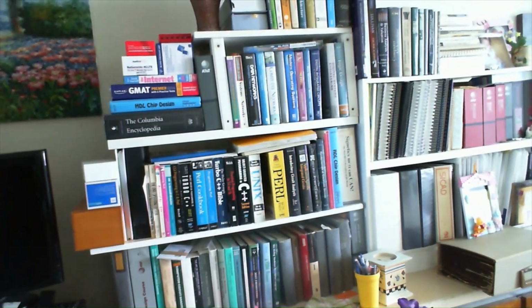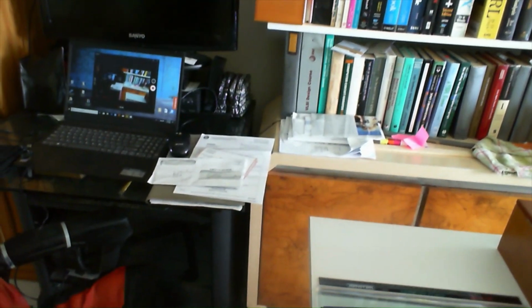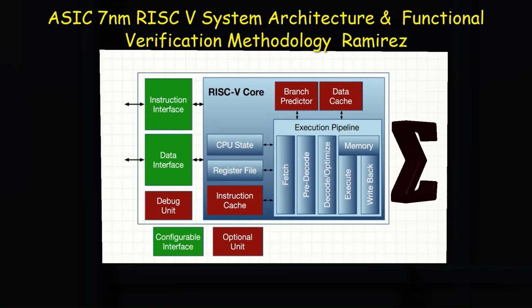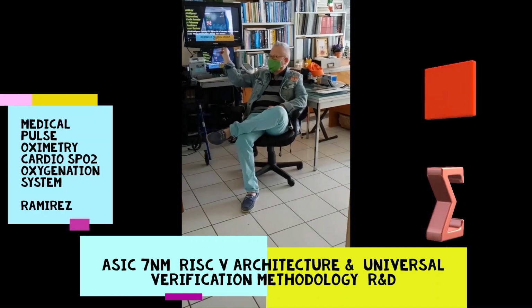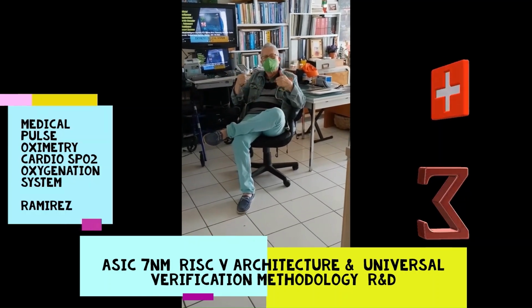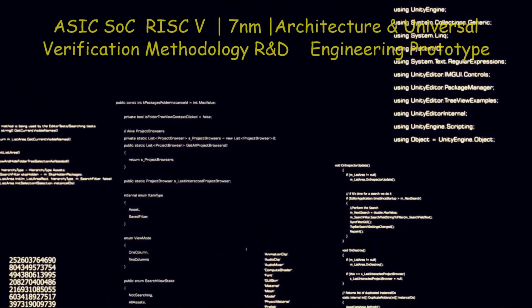The extracted netlist from the GDS is what is used in the formal scan chain proof. DRC is checked by OpenLane for each small segment of the project, and then again at the top level when I combine all the projects.